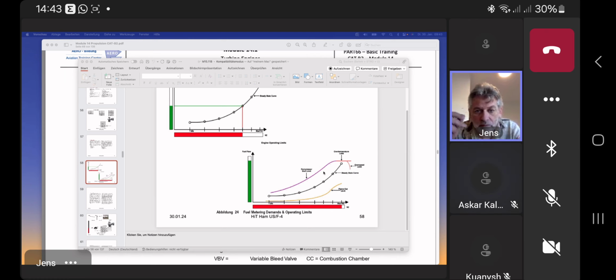This is important because we talk about takeoff. It's according to N1, not N2 as mentioned here, because N1 provides most of the thrust. And the metering valve takes this into consideration: I have to provide a certain N1 to have the takeoff thrust, but what is my condition? Without that, we risk destroying the engine.